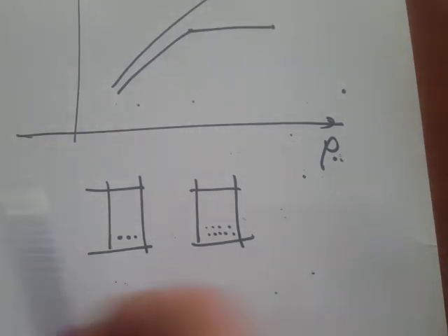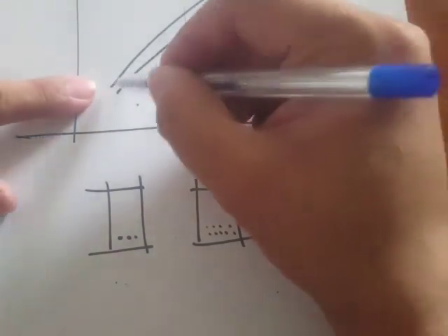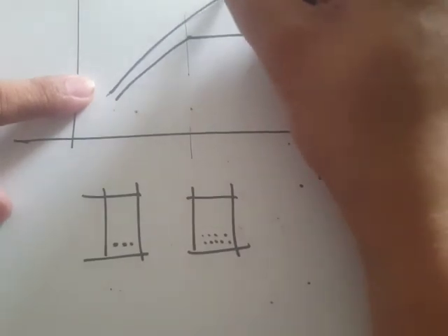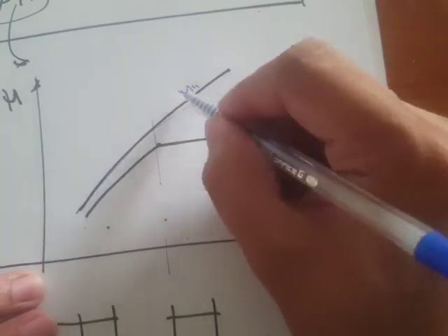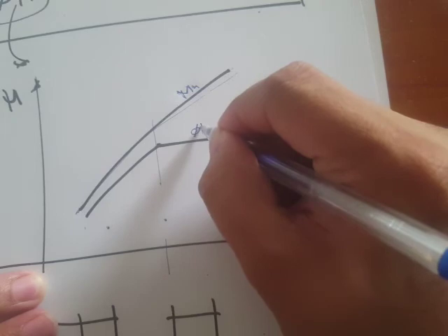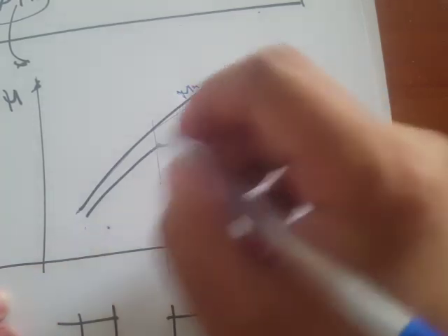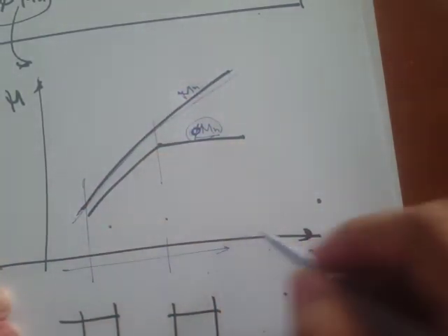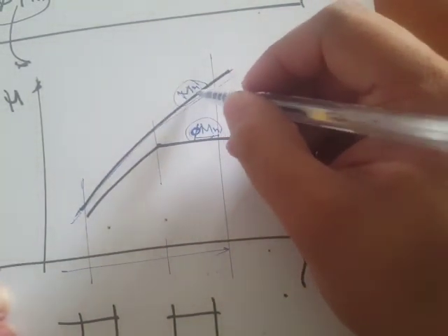Except that for some value of ρ, for the nominal capacity, yes, the more you increase it, the more capacity. So this is Mn, the first curve, the nominal moment capacity, and this one is the factored moment capacity, once we apply the strength reduction factor. Here you'll see that the more you increase the steel ratio, you get an increase in the nominal moment capacity.